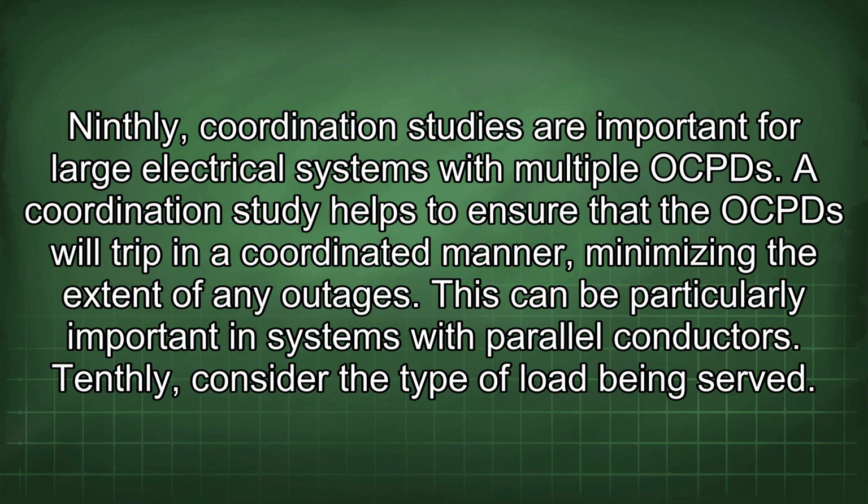Ninthly, coordination studies are important for large electrical systems with multiple OCPDs. A coordination study helps to ensure that the OCPDs will trip in a coordinated manner, minimizing the extent of any outages. This can be particularly important in systems with parallel conductors.